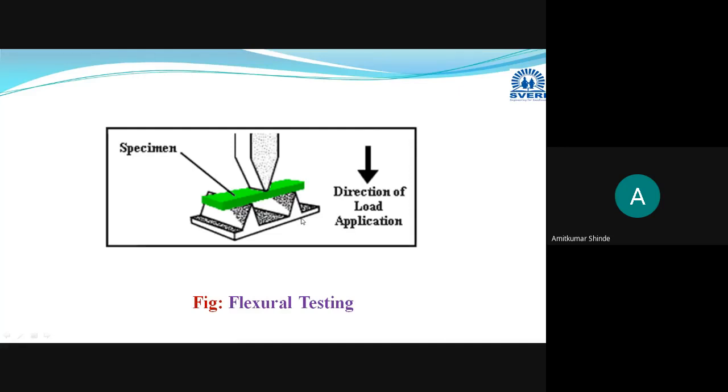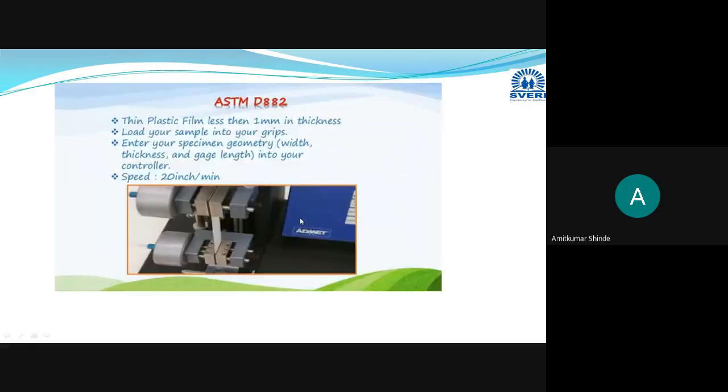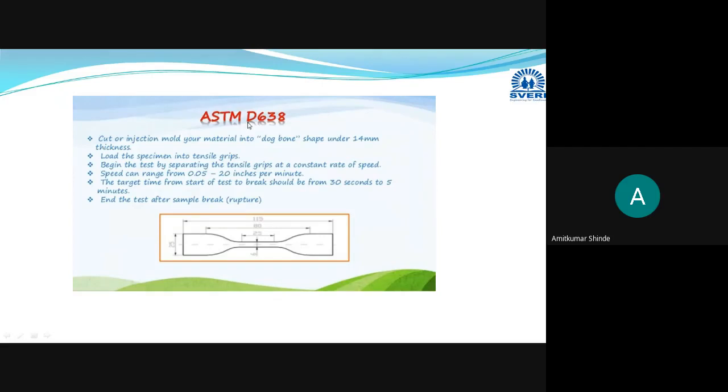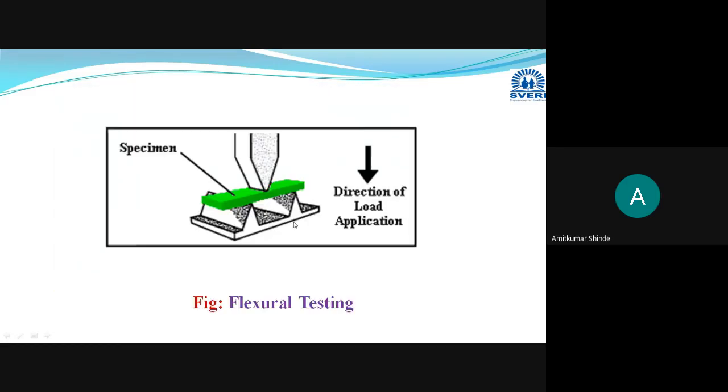Now this flexural testing is conducted here with the ASTM standard D790. For the tensile testing, we have used D638, and here we are going to use ASTM D790.